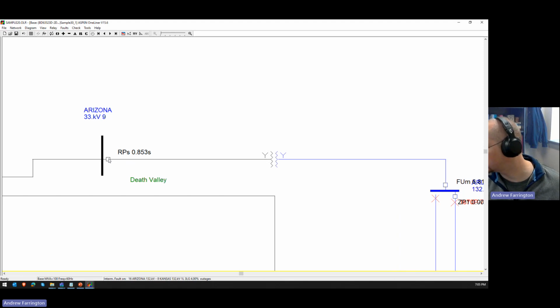And then I should have also said the longer restoration time, which I just kind of covered here, but somebody has to physically go to the site and get up in there, into the truck maybe, and replace the fuse, even if they found the fault, say, on the way to the substation. They still have to replace the fuse in order to re-energize it. Whereas if they had found the fault on the line, they could have just closed the recloser. Anyway, I wanted to cover that because I thought that was a really good question, and I think those are good things to keep in mind.